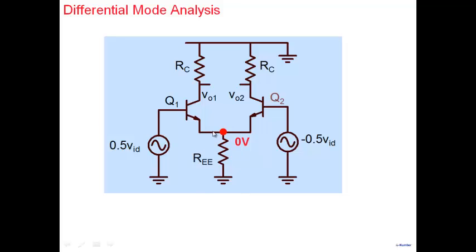All that you're saying is that under small signal analysis, you can assume that this point is at 0 small signal voltage here. It's not a real ground here. Okay? Real ground is over here. That's the real ground here. This is more like a small signal ground here.